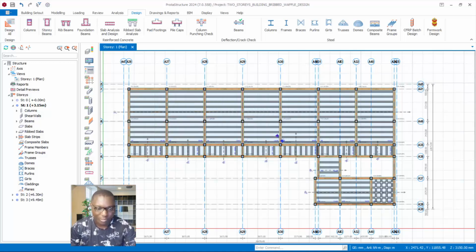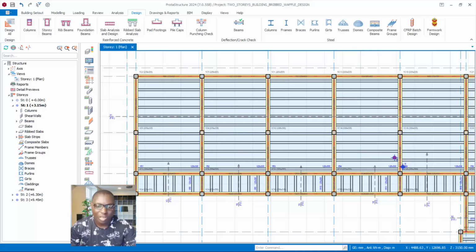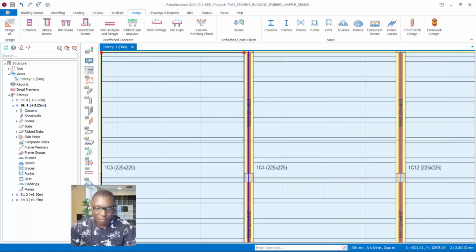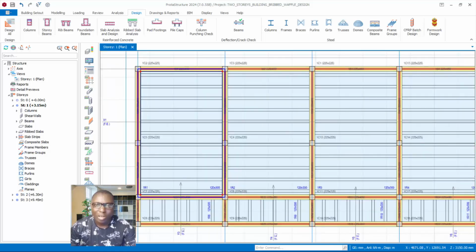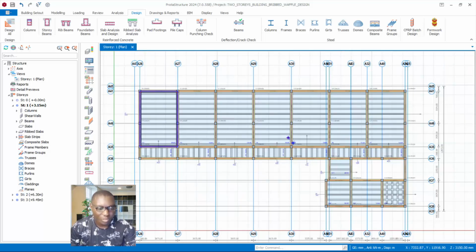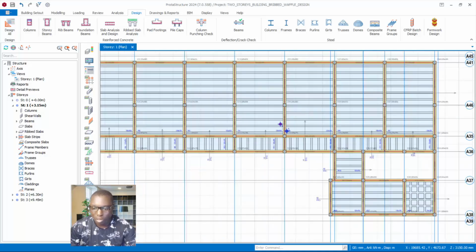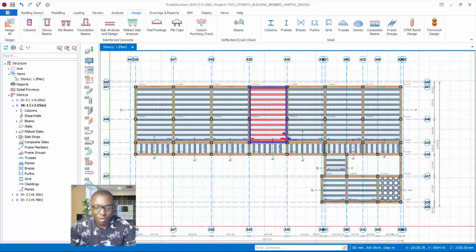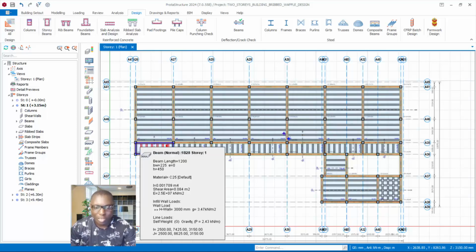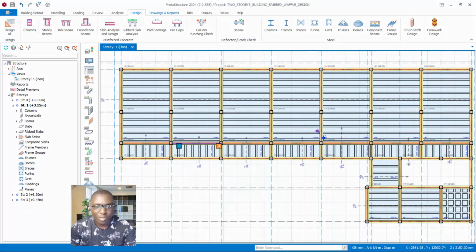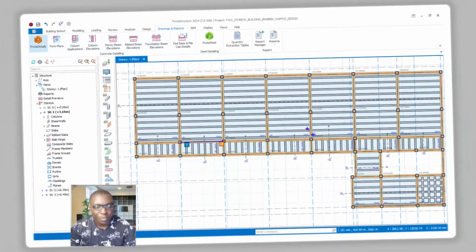We have resolved that successfully, which I said, if you want to still have enough space, you can increase the width of these ribs from 120 to 150 millimeters successfully. Okay, so at this point, we will now have to see how we can move all of these drawings to Prota Detail. If you come to where you have drawings and report, I see Prota Detail here.